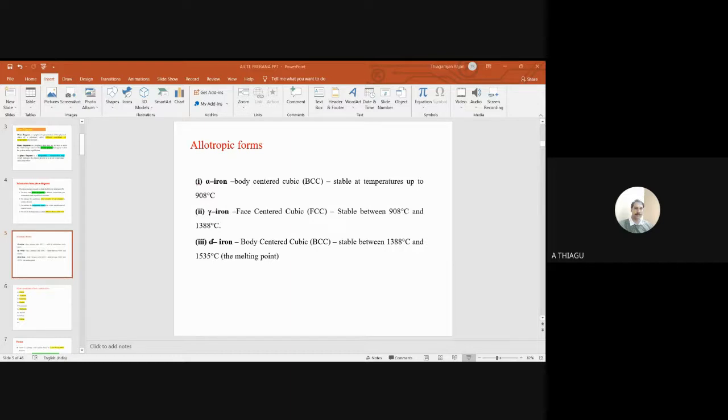But in the case of cast iron, we have a range of carbon from 2 to, you can look at the bottom, 4.7 as the maximum. In some cases 2 to 6.67, but this is a theoretical maximum limit; practically they are not beyond 4.7. So 2 to 4.7 is the maximum weight percentage of carbon that comes under cast iron. For cast iron, you can give many examples. A motor casing is a good example of cast iron material. Couplings, flange couplings. Okay,